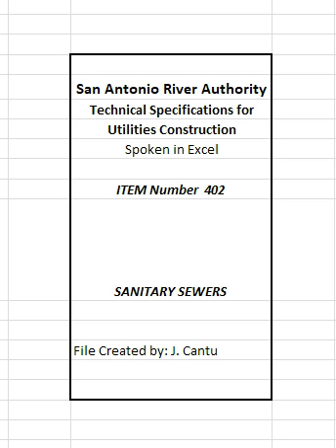3. Subgrade filler. When laying pipe in unstable materials as defined by item 404.2a.2, Bedding, the contractor shall, when directed by the field representative, under-excavate and remove existing unstable materials or rock, as directed by the field representative, and replace with subgrade filler material as directed and defined by item 404.2a.3, Subgrade filler.